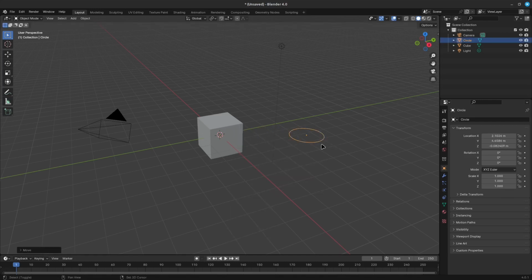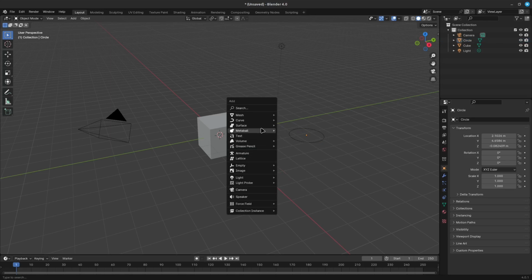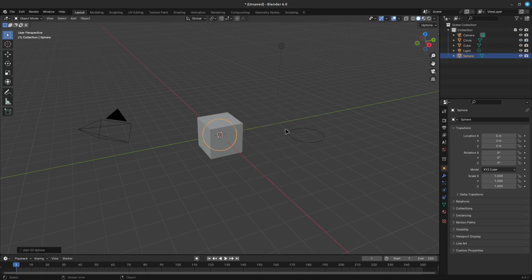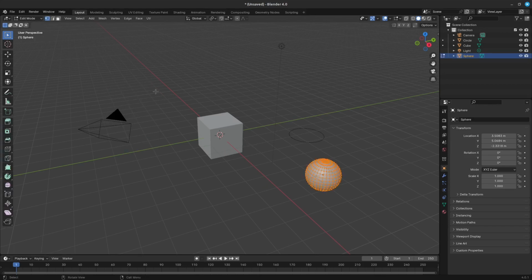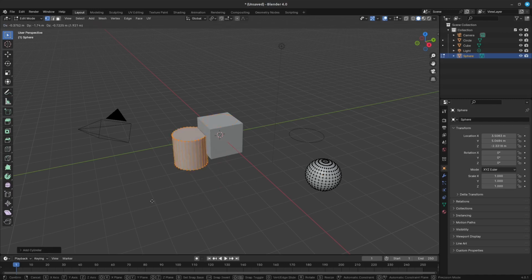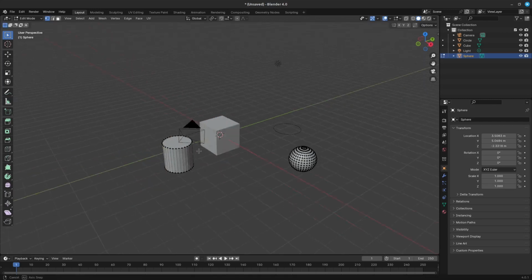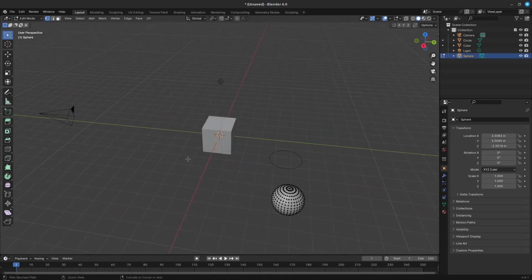It is immensely helpful. We will begin with extruding a region. First, make sure you are in edit mode. Remember, you can press Tab from object mode to change quickly. To extrude, we will need to select some vertices that we want to extrude. Then we will need to go over to the toolbar here and select the Extrude Region tool.